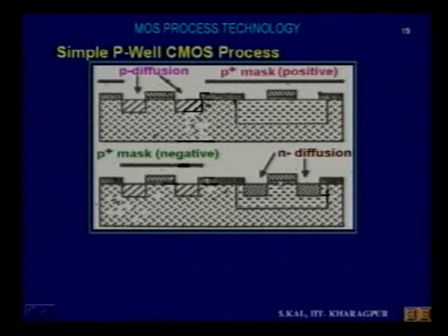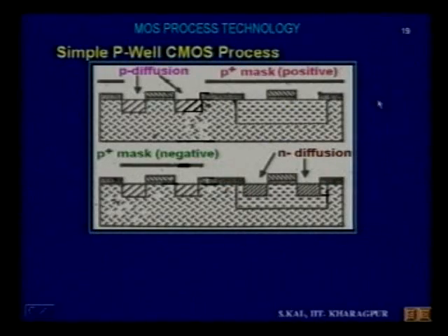Similarly, here the polysilicon will be doped, and that is also good because its resistivity will be less. This region is again the field region, so it will also be doped with N dopants, but since the thickness of the field oxide is large, the dopant will not reach below the oxide. Through this region and this region only you are getting N plus source and drain.